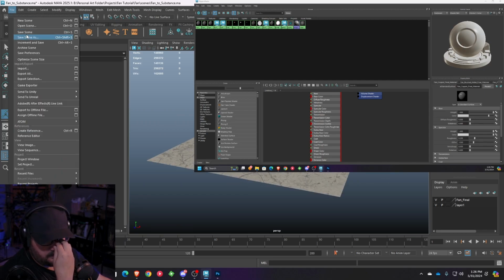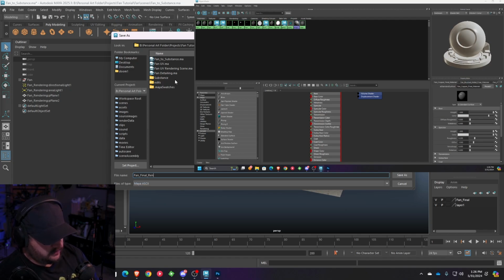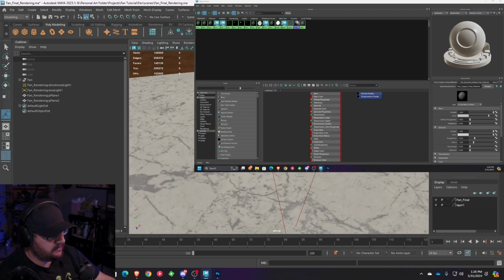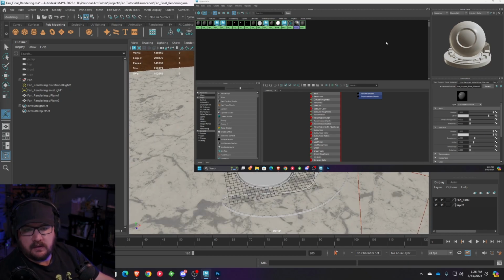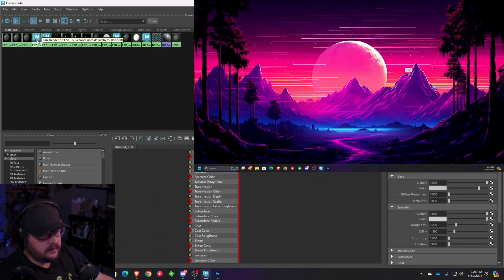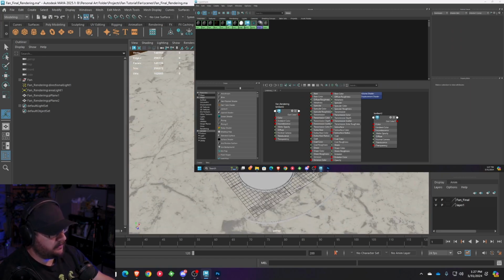I'm gonna go File, Save Scene As fan_final_rendering. This is going to be our final project that we're going to be working in. All right, so we have our fan set up. Everything's good. We have our new materials set up. The only thing you may notice is it imported a bunch of materials that we don't need. So we're going to just delete these. Okay, so we have our materials.